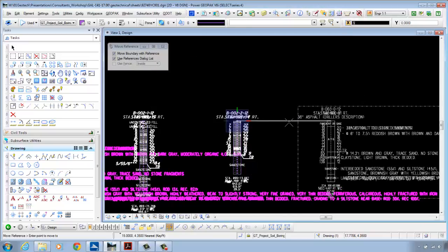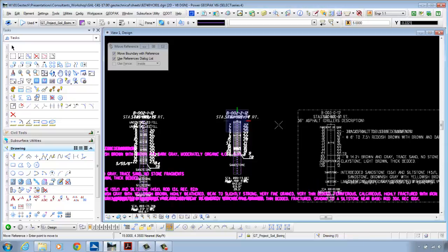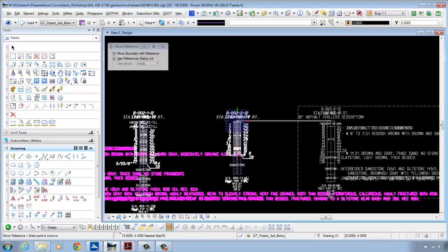If you ever need to do this, to add additional borings to your design model at this stage, maybe you have borings in 2 different GINT files, maybe you have 2 different phases of drilling, those borings must all be aligned in a straight line by the top of the boring graphic elevation. That's a requirement of the Move to Models tool that I'm going to show you in a moment.